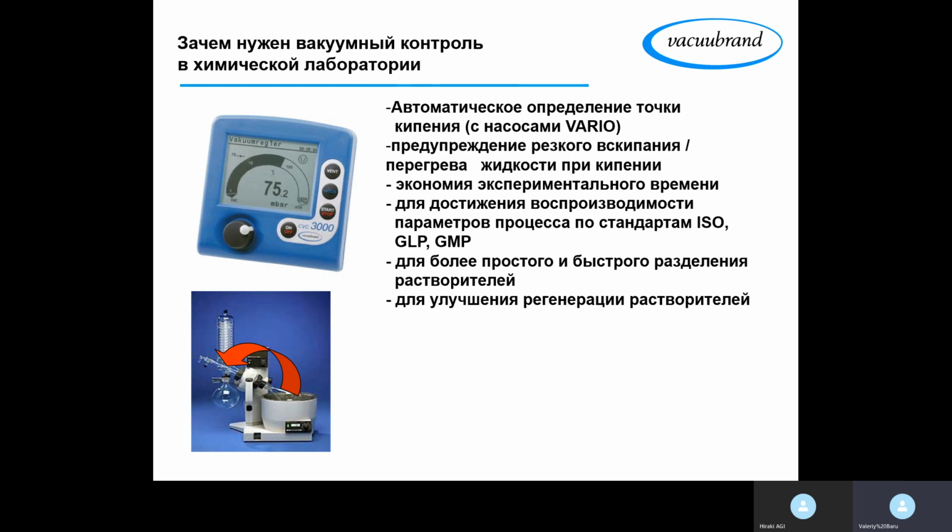After the first second, it gets the second value of the vacuum inside the system. Let's say within 1 second, it went from 1000 millibars down to 950 millibars. Delta P is not zero, so the pump pumps out the gas. The controller understands that. After second number 2, let's imagine it goes down to 900 millibars. Second number 3, 850 millibars, and so on and so forth.